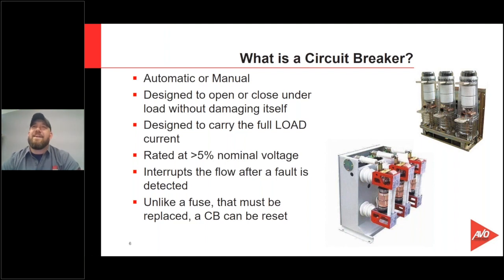But either way, they're like the Rock. It does what it's told. It's just a big piece of equipment. It's rated for a particular amount of voltage. It's rated for a particular amount of surge and current. It's got a BIL. It's got a medium. All right, it's got a way of extinguishing the arc, of course, the medium. It's rated for a particular nominal voltage, and it just opens and it closes.